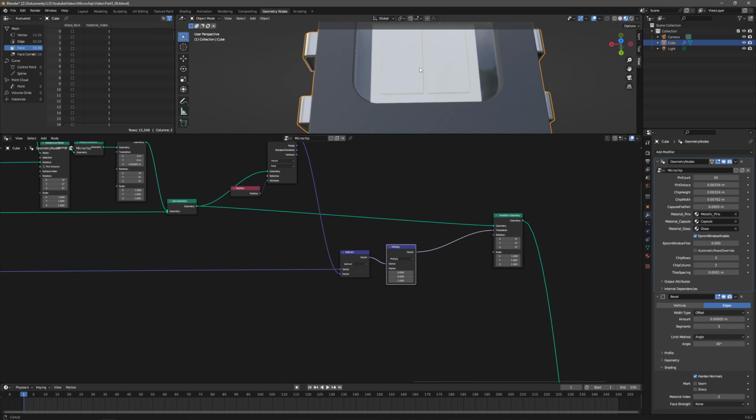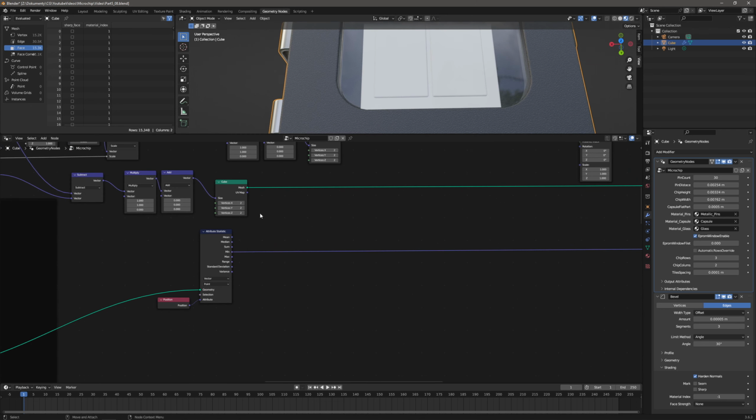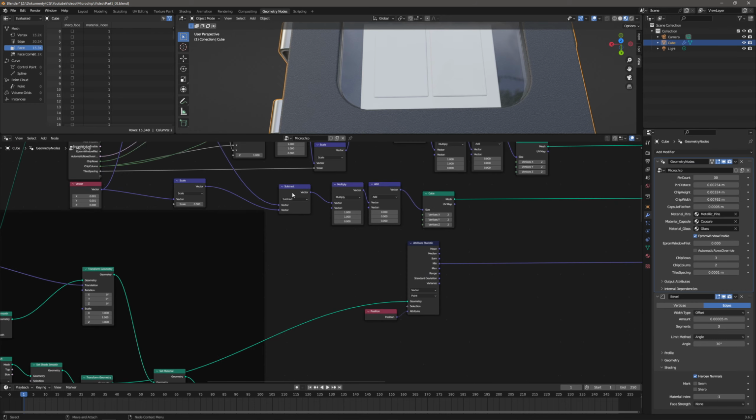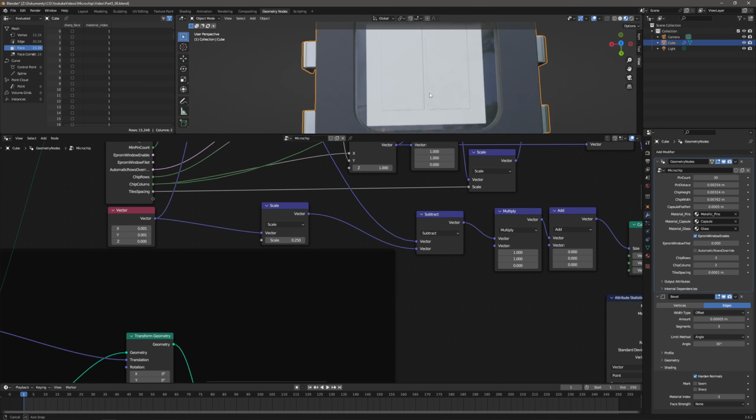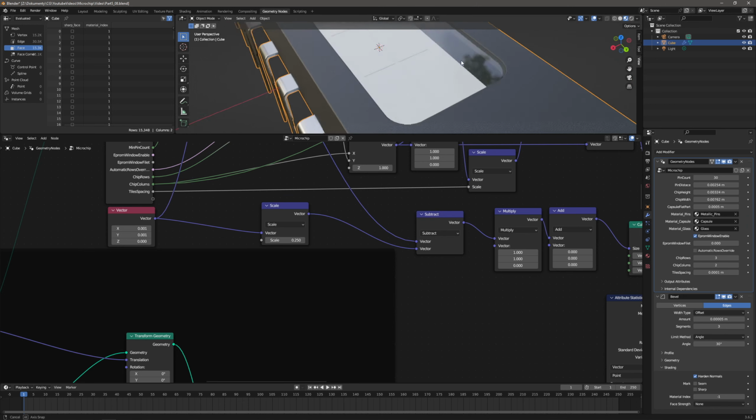What I think I will have to do is enlarge the base plate just a little bit. So I will scale it with some factor like 0.75, I think. No, it's subtraction, so 0.25, and that should give me enough space for the contact fields of the wire leads that I will add later on.